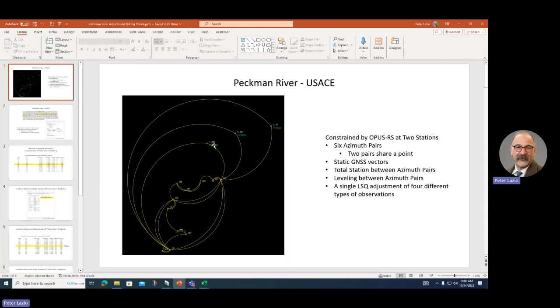We ran into one a couple of years ago, a 100-foot tall hill, and the top of the hill was a foot off if you were on a level up to it, from what the GPS said. They ran a plane on the bottom side, because they didn't want to climb to the top when they localized. So it hit zeros, but when they got to the top of the hill, they were a foot off vertically. Not everything was built by the time we got out there, because we were just doing some curb work, so it was one of those, well, this is what we're rolling with.